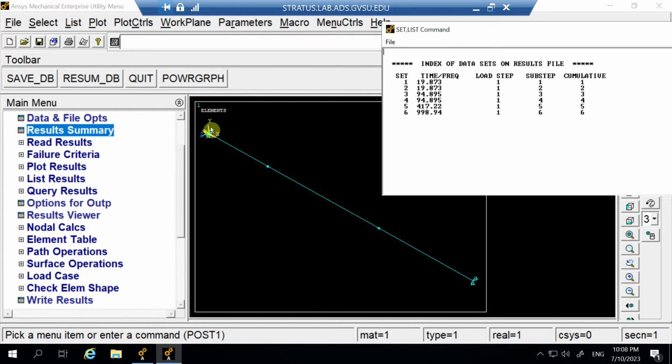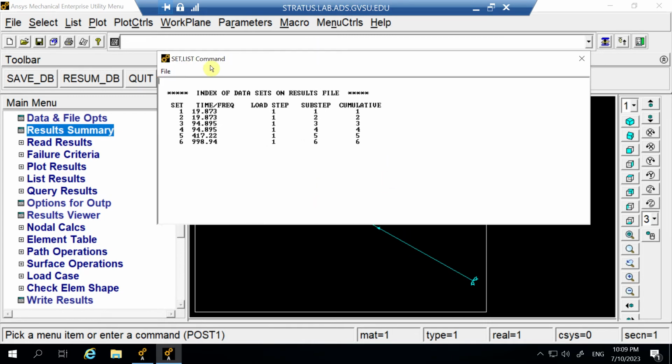In those two planes, natural frequencies are going to be the same. So as you see, the first two are repeated. 1 and 2 are the same, 3 and 4 are the same, but then number 5 is not repeated. Probably that one is associated with twisting of the shaft.